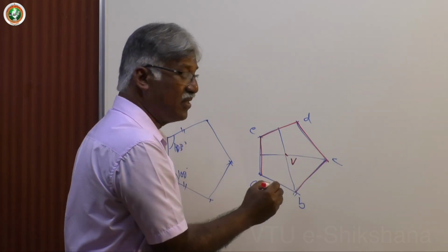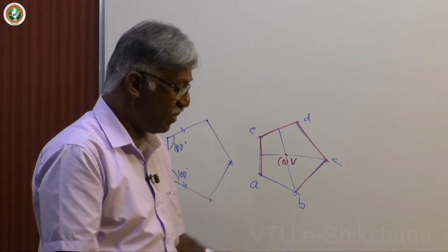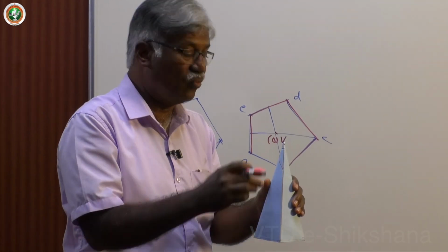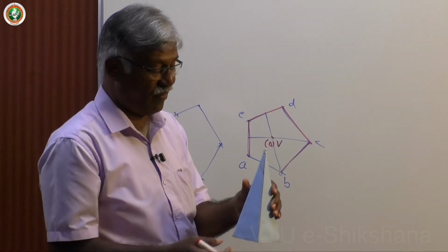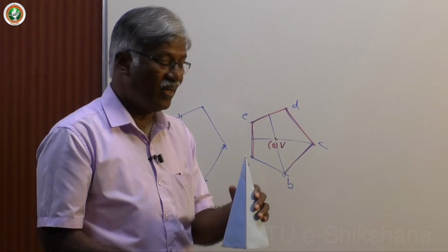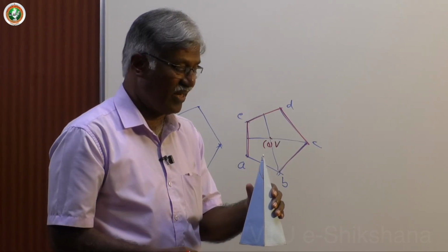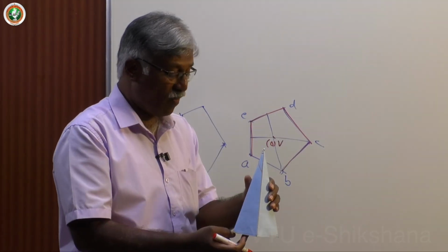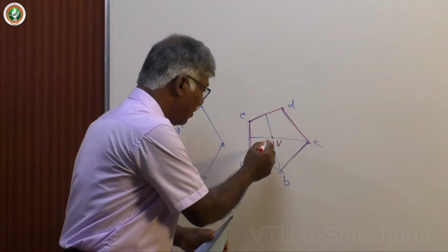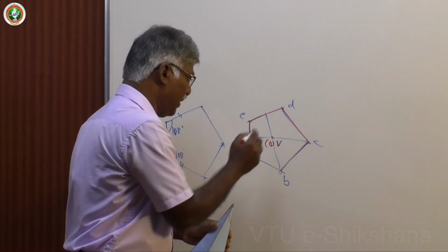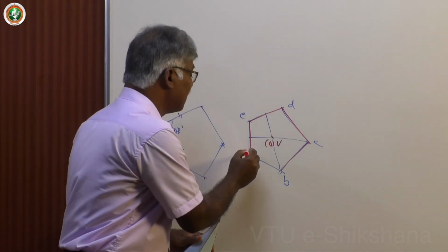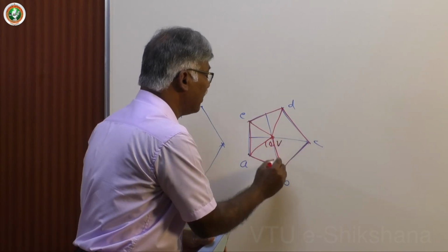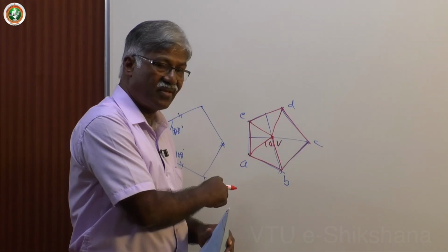This is the vertex and this is O. I always use VO, vertex V and O. Why you should not use OO1? You can use it, but there will be confusion, and we end up with trouble afterwards at the end, when completing the problem. Now this is V, this is O. So O is not visible and V is towards the observer. Next, join all these corners. This is what we normally forget, this is a must.